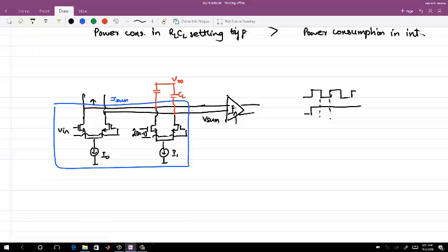Yeah. So at the falling edge of the clock, you discharge or charge to one fixed potential, right? And that is being done by having what we call a reset. This is working at clock speed. This is PMOS, so it's an inversion there.